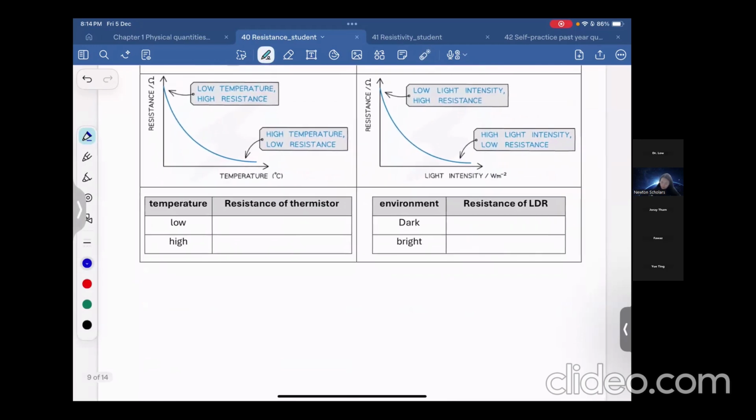At here we can add some points on how it works. Number one, when temperature increases, the thermistor will release more electrons. Electrons are very important for conductivity. If you have more free electrons, your conductivity is very good, it is easy to conduct electricity. So conductivity increases, which means it allows more current to flow.